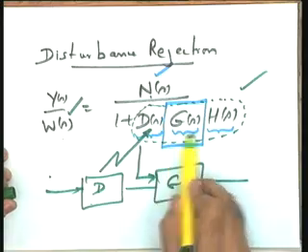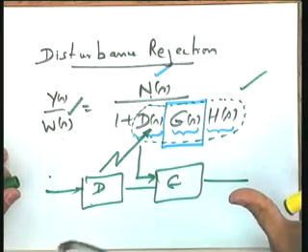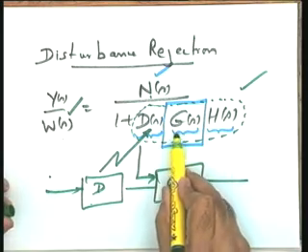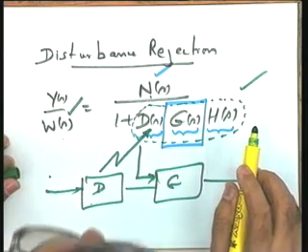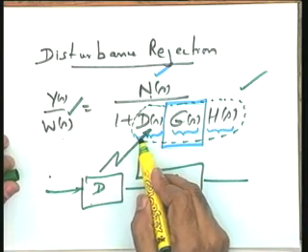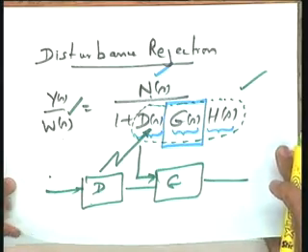Okay, but as a thumb rule I may tell you that we will not touch G(s) and H(s). These may become our fixed components. Once you have taken care of, maybe by adjusting some open loop gain, the loss of gain, after that the loop gain is primarily being increased through the controller design D(s). Okay,